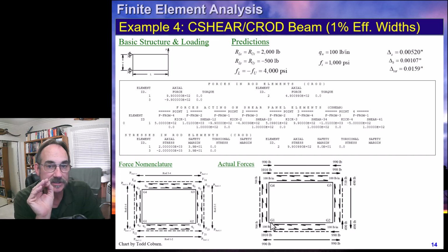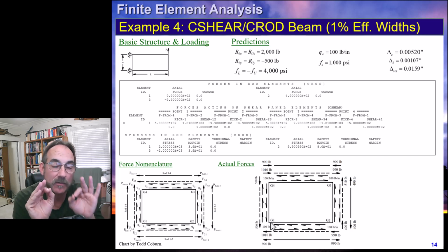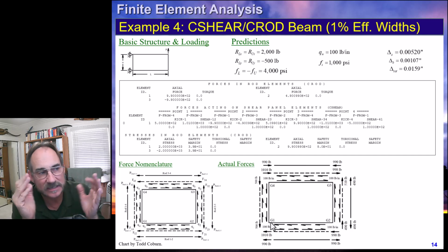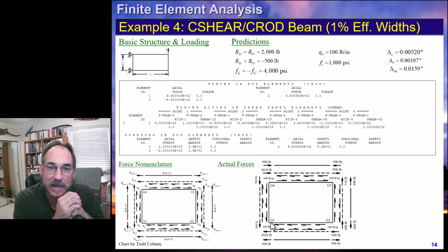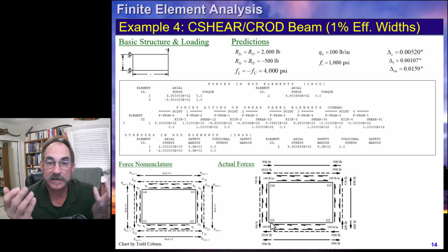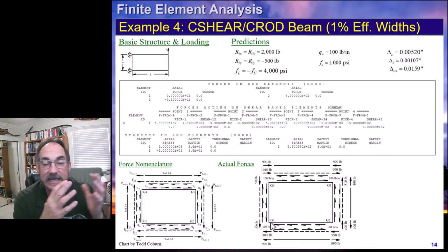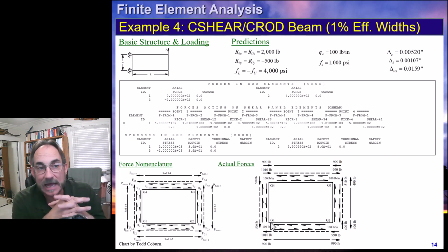Now, the careless finite element modeler will run this model, look at their rod stresses, conclude that the axial stresses in those surrounding rods is 2,000 psi, and they will be 100% wrong. Only half of the stress. 2,000 psi is not very much, but if this were a real loading, that could easily exceed allowables.